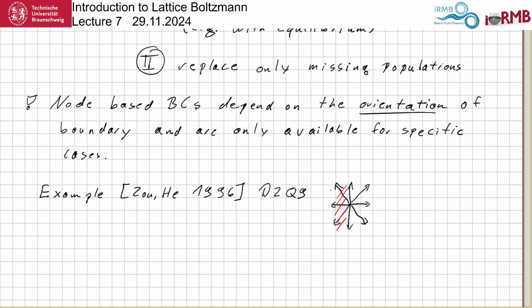So this is their domain. They come from the complex fluid stuff, so simulating blood and these things, and usually these things have very low Reynolds number. It's very low Reynolds number flow. So in this context, the Zou-He boundary condition kind of works.